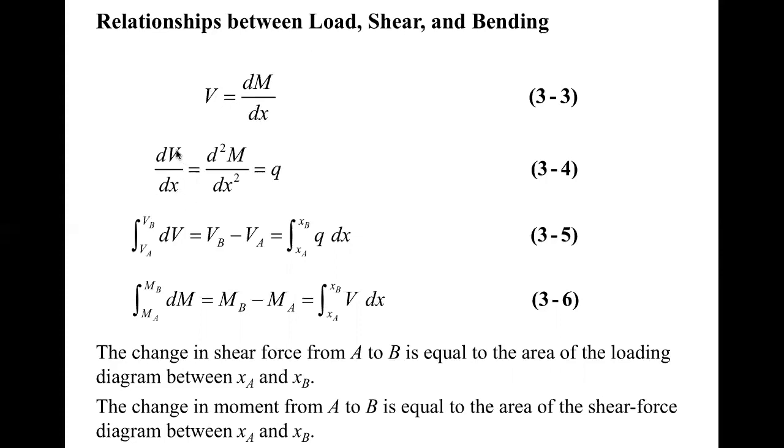If you take dV over dx, you'll end up with q, the load intensity. Usually, in a particular application, we give you this function q, and then you can find the V. How do you find the V? You just do integration.